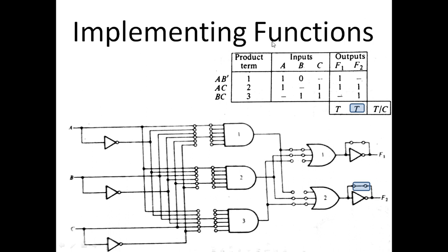And then by looking into the two Boolean functions, we decide about the size of the PLA, the number of product terms, the number of sum terms, outputs and inputs. In the current example, we had three variable Boolean functions. So three variable Boolean functions means 3 inputs, which is the value of n. By representing the two Boolean functions in the sum of product form, we at the end got 3 product terms.